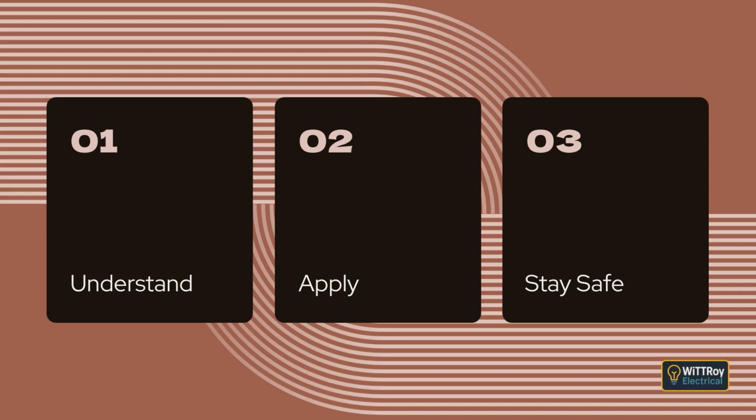This allows the fault current to flow safely and ensures the voltage rises high enough to operate the protective device. Second, the protective device, whether an overcurrent device or an RCD, must disconnect the fault fast enough to prevent danger. The basic message is: a good earth connection plus a fast protective device equals safe fault protection.